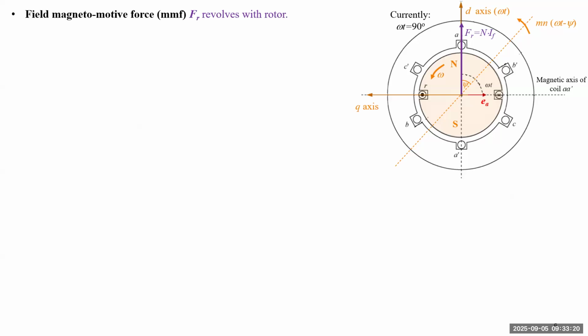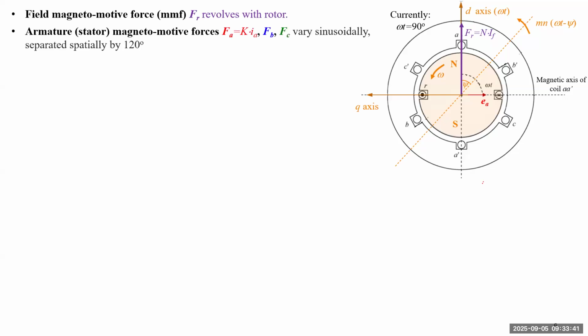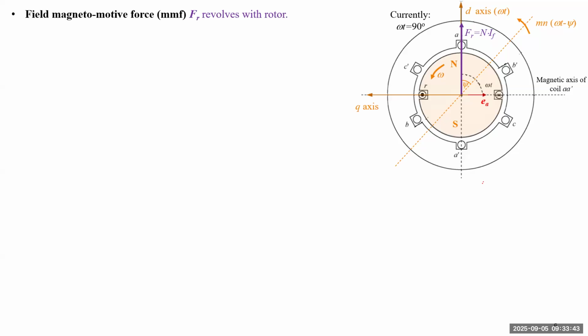All right. Okay, so this slide is a very busy slide because I want to integrate everything into the same slide to help you understand the modeling, the key part of modeling, which is how to determine the phasor for the induced voltage EA. Here we just draw EA as the voltage induced in winding A, but we still need to determine the direction and the magnitude.